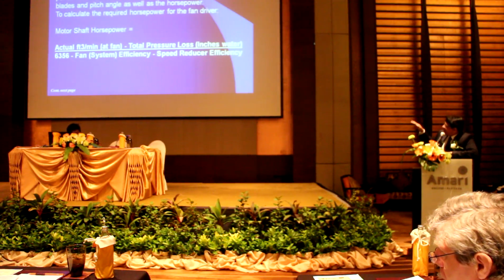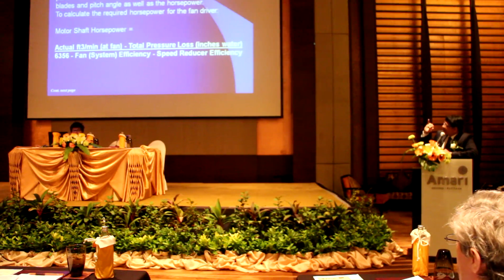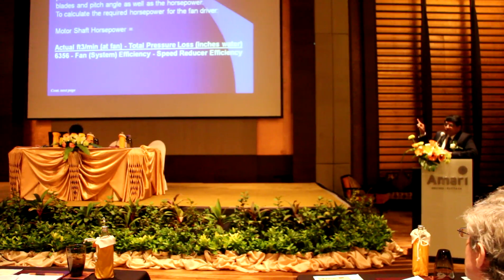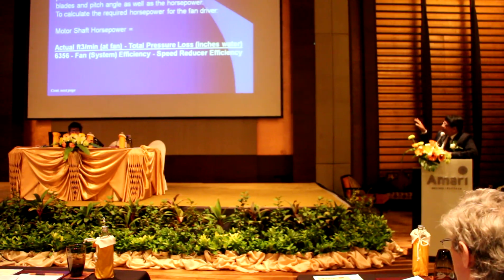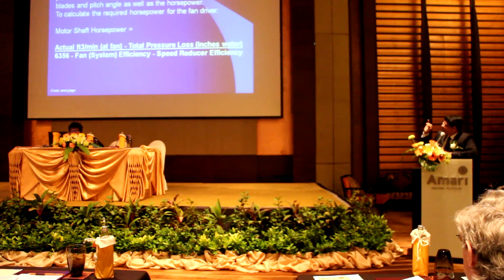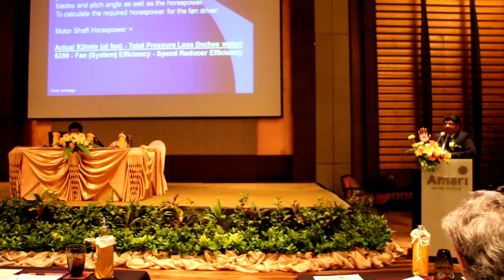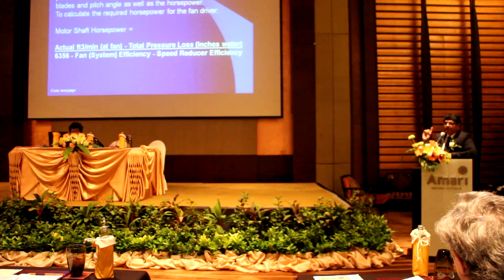So now you can see here, for any duty condition, your actual airflow is fixed, your total pressure loss is fixed. Both being constant now, you have only two things at the bottom to reduce your motor shaft power. That's your fan efficiency or the speed reducer efficiency. We are not thinking of anything in the speed reducer efficiency because we are hoping that your system or drive is in proper condition.